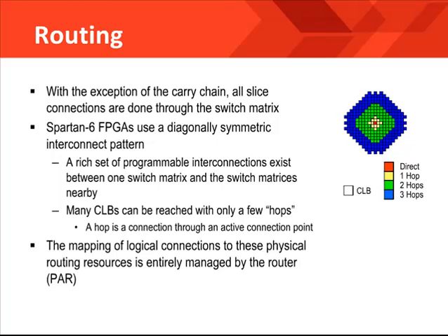The implementation tools select an appropriate routing that may include different kinds of routing resources. The solution that is routed is designed to try and meet your timing needs. To do this, it is important that you add timing constraints with the ISE design suite so you can communicate your timing objectives to the implementation tools. This will allow the software to choose the most intelligent routing solution to meet your needs. In fact, the mapping and placement of logic resources is handled by PAR, the Placement and Routing utility.